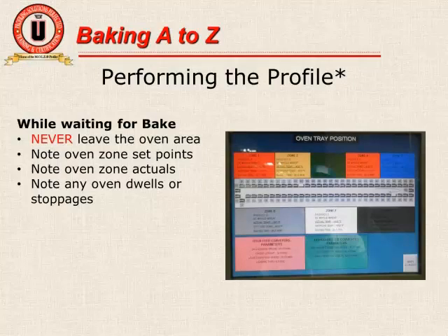That's worth noting because the profiling of the last loaf through an oven is way different than the profiling of the first loaf through an oven. So it's worth noting. It's best to profile a fully loaded oven. That's going to be the best overall information you can possibly get. I realize that in like all cases you can't do that. But note the conditions of the oven, especially if there's any large gaps in product. Keep an eye on that stopwatch.